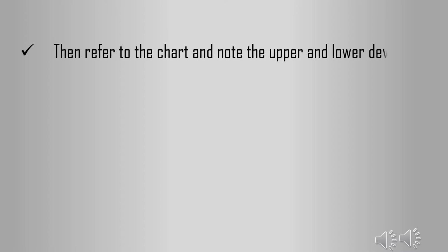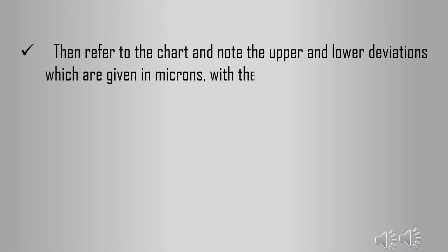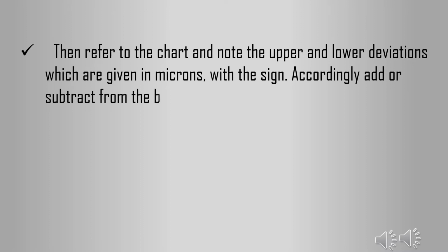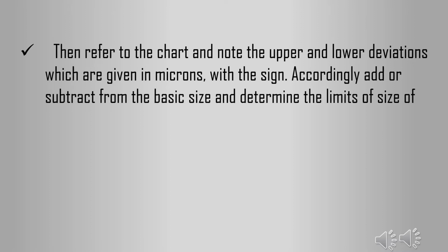And the last point is, refer to the chart and note the upper and lower deviations, which are given in microns, with the sign. Accordingly add or subtract from the basic size and determine the limits of size of the components.